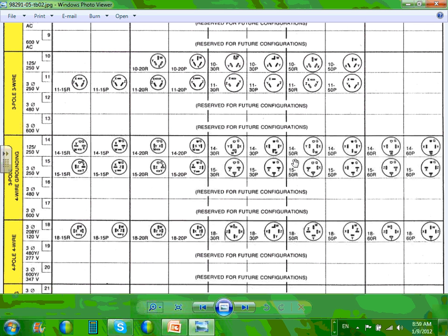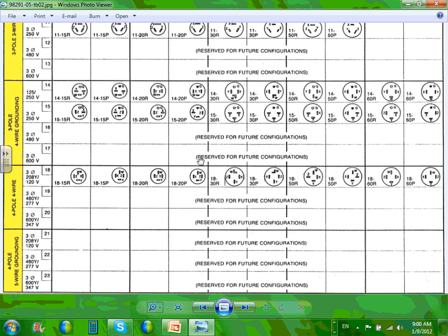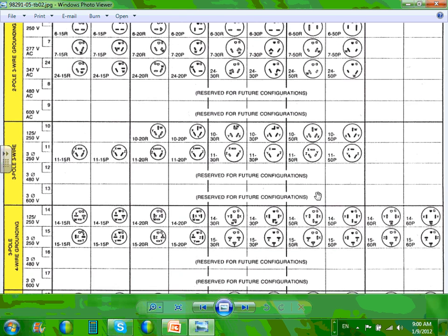Where they can use them, commonly used: machines, manufacturing, assembly. You have the plug coming in, or you can have a disconnect too. So you have a disconnect at the top, and you have a plug coming out of that disconnect. You have the plug, and you have the receptacle. You plug it in. Most of these are locking type receptacles where you can plug and lock. This is plug-in, the one that has a twist. You don't have to know all of these, but this is a very common application for the receptacles.